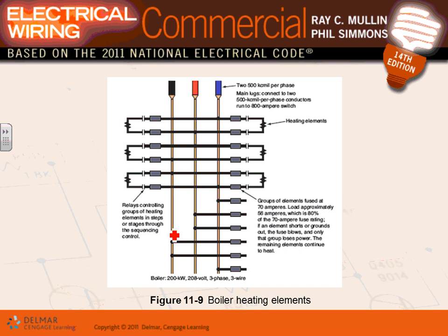Okay, this is how it works, guys. All this is 3-phase. Look at that. We're bringing 3-phase, 2 sets of 500 kcm to this boiler. The way they do it, guys, if you need more heat, they start closing contacts. Certain contacts closing at a certain time will give you more heat. That's how they run these and they're grouped. It looks like listed 75 amps each one of them. Fuses that fuse them. So these heating elements, instead of having one heating element, they have multiple of them, and they turn them on and off based on the need. If you need more hot water, a lot of hot water, they turn them all on. If you need just a little bit of hot water, guys, they turn a few of them on. Does that make sense? Now all this is happening inside the hot water.